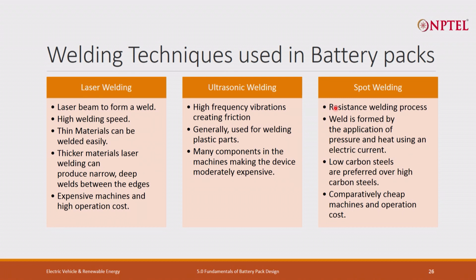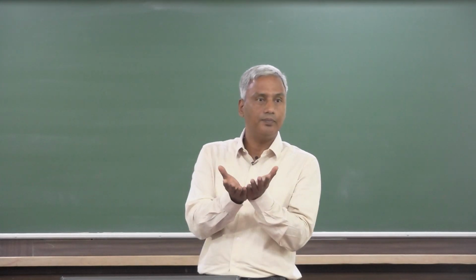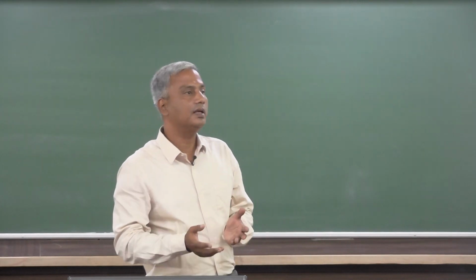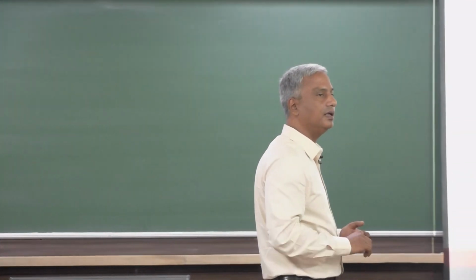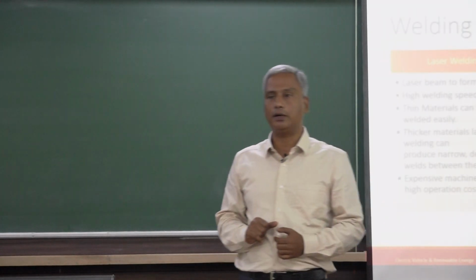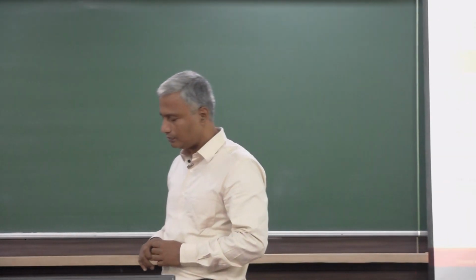Ultrasonic weldings are good for very thin materials. If your current requirement is very small, in such cases ultrasonic welding can help. It is also very good for plastic enclosure welding. When you have to maintain the IP ratings and other things, ultrasonic welding works well.